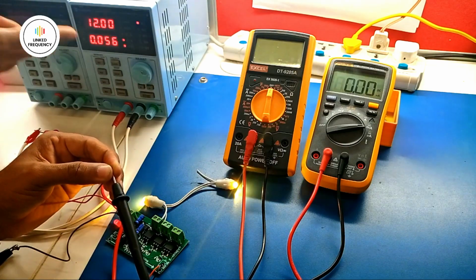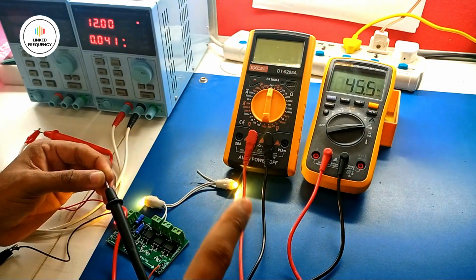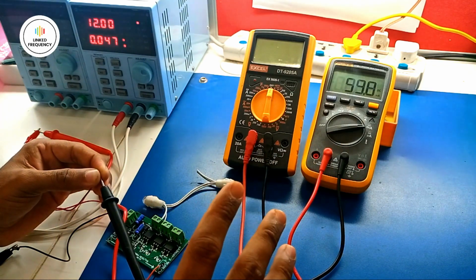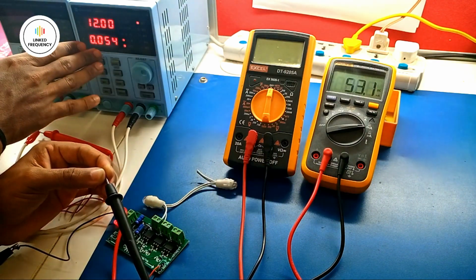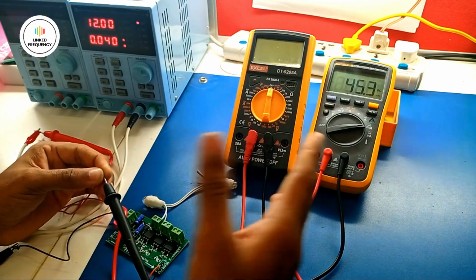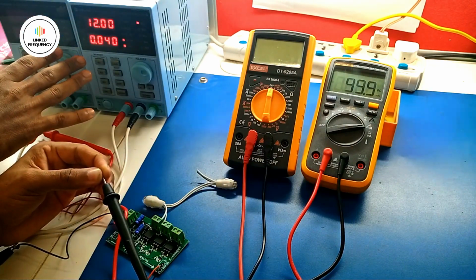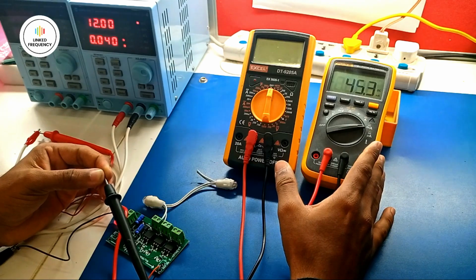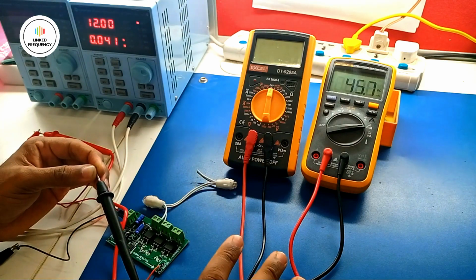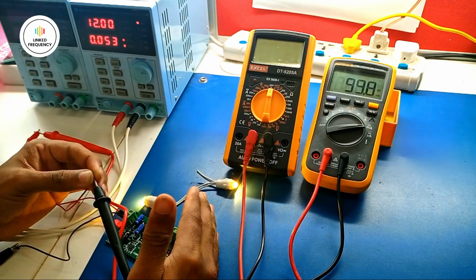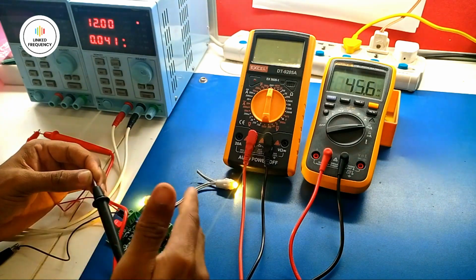I'm going to turn on the circuit, and you can see that this circuit is working now, and the current showing over there is 45 milliampere to 59 or 60 milliampere, which is not near to this particular value, because it is going from 40 to 58 milliampere. Here it is showing 45 milliampere. There will be a difference because this is not having a proper sensor inside, whereas this is a very standard digital multimeter. That's why I trust this one, and I believe this circuit is consuming 45.5 milliampere at the load level when the LEDs are turned off, and it is consuming 58, 59, or 60 milliampere when the LEDs are turned on.